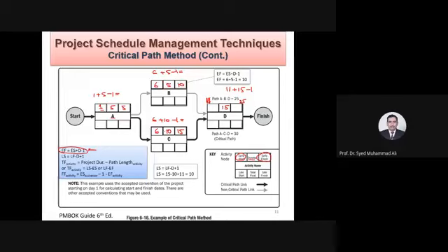Yes. Let's move further. Now, when we are coming from this path and reach this D, whatever is D activity, concreting of slab, for example. Now, please tell me, when should D start? Sir, 16. 16. Now, there is an issue. We have two values over here now. From this path, it tells us start activity D on 16. If we come from this path, it says do the activity on 11th. Which one are you going to prefer as common sense? The lesser one.